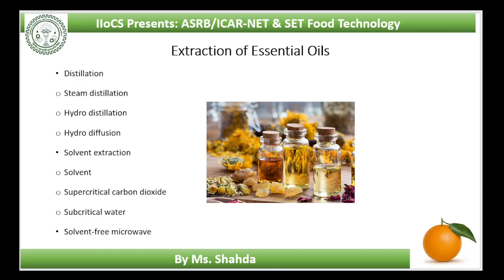Using oregano as a raw material, solvent-free microwave extraction offers significantly higher essential oil yields compared to hydrodistillation. When microwave power at 622 watts was used in solvent-free microwave extraction, process time was reduced by 80% compared with the conventional process.